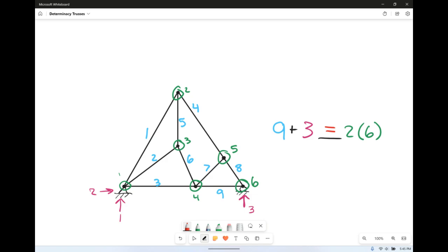So even throwing in one other member here, we're going to make another triangle in this little area. So we included one member, that gave us one joint, which actually gave us a second member if you want to think about it this way. So we had 2 for the joint, and we actually created 2 other members, which is why this still worked out.